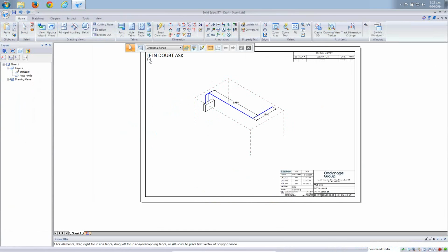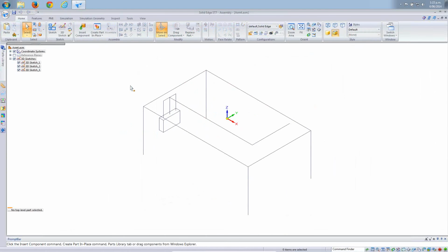that particular drawing was generated from an assembly, and I've just changed some of the line styles. So here's the outline of the room with some heating or ventilation or pipe work or whatever it is, a schematic of that and the unit that it goes into. We do a quick double click, that takes us into, in this case it's an assembly, but it could be a part file, and I've generated 3 sketches, one for the room, one for the routing, and one for the unit.